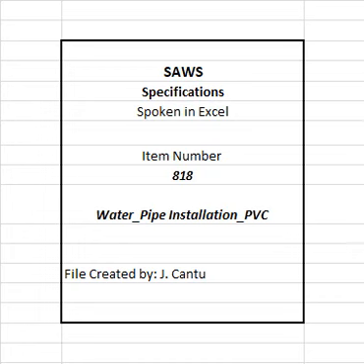D. Wire shall also come up to the top of valve extensions and fire hydrant stems, as directed by the inspector. E. Tracer wire shall be utilized for location purposes and taped directly to the top of pipe. F. Tracer wire shall be of solid core, 14 gauge insulated, and shall be taped to the main in minimum of 10-inch increments. G. Detection tape shall not be used in lieu of tracer wire.